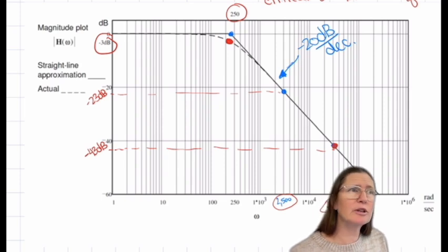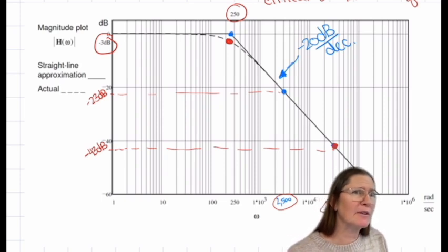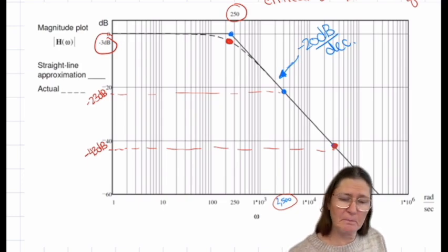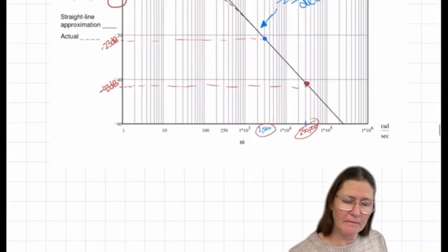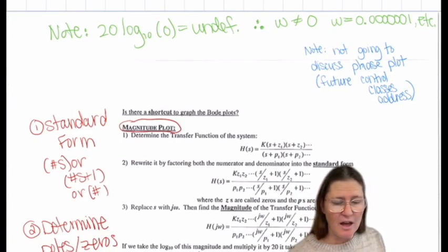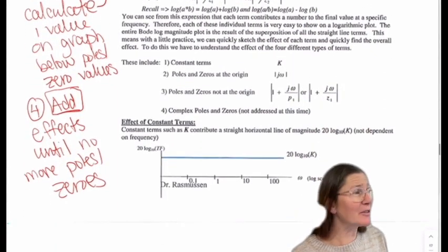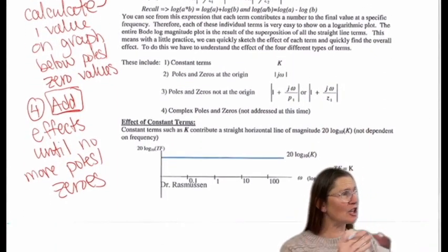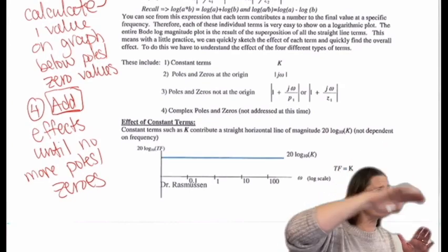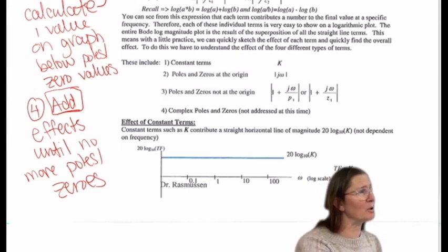So how do I know that it goes down by minus 20 dB or up by 20 dB? That's kind of the next step. Is it always 20? Or is there a reason why? Yes. If you plug in the values of omega after a change, you'll actually see it's always a plus 20 for what we call a zero and always a minus 20 for a pole.